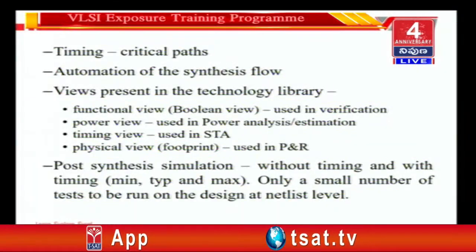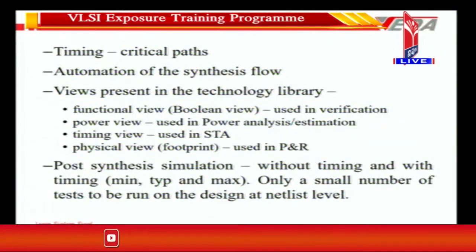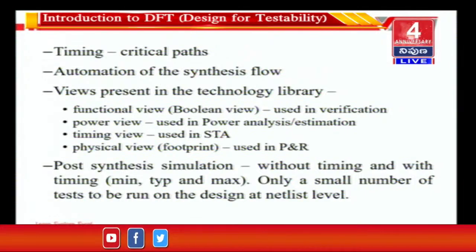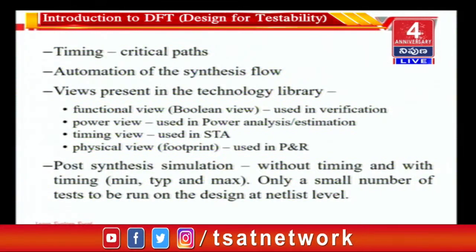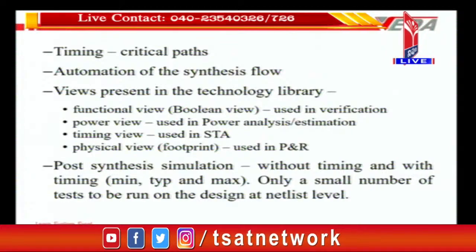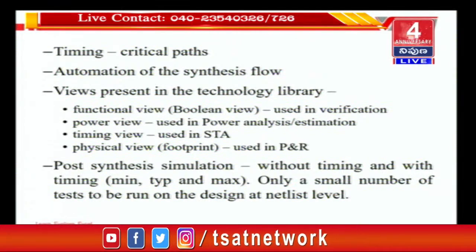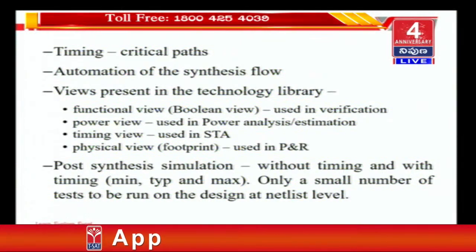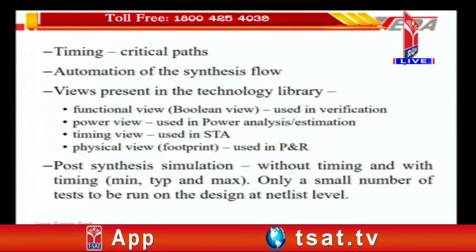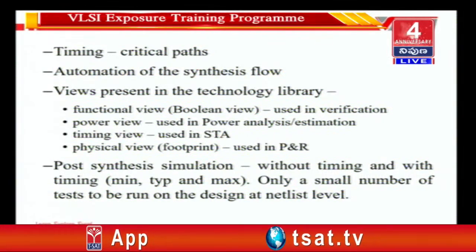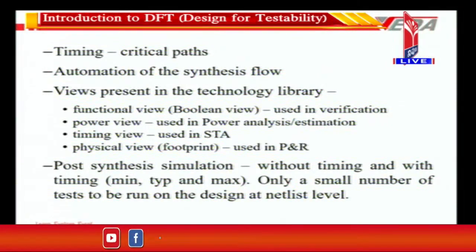Then let us look at the synthesis aspect. This slide I should have put before the break, but let us go ahead. We have critical paths in the timing, and the timing report from the synthesis output will also tell what the critical paths are, what paths have delays close to the time period of the clock.